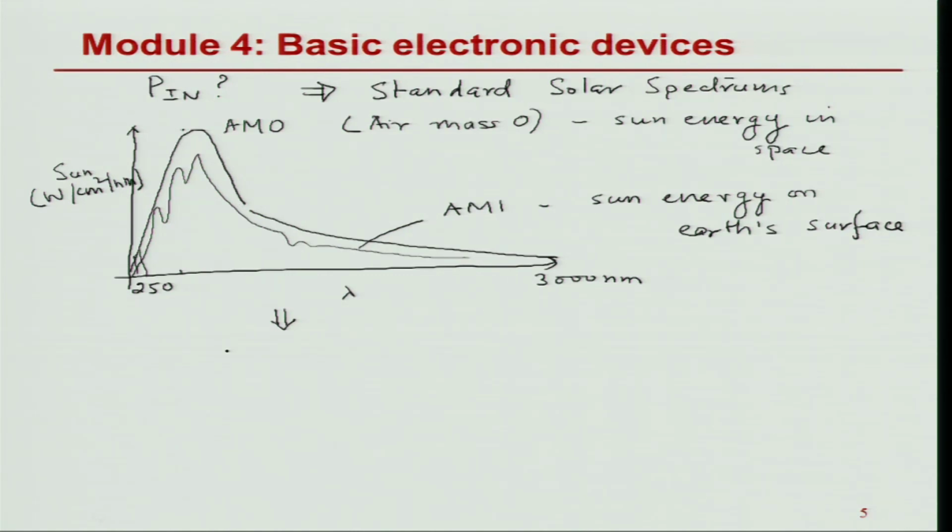It becomes easier if I change this watt into number of photons, which I can easily do because each photon is h nu or hc by lambda. So I can calculate for each joule how many photons I have, and the convenience comes from the fact because we know that each photon is responsible for one electron hole pair. So then it allows you to think in terms of number of electron hole pairs generated, and that is an exercise that helps in further analysis.